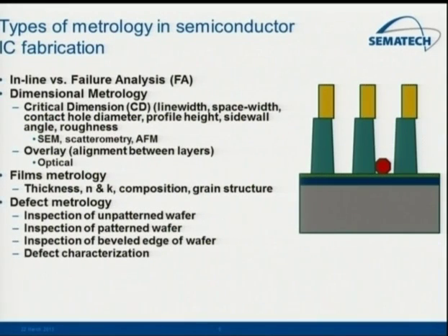In the sense of what do we measure in semiconductor manufacturing? Now there's actually two types of metrology you could think of. I'm going to talk today almost entirely about inline, which is the manufacturing metrology. So these are things you do when the wafer is running through your process line. Which measurements do you need to control your process?